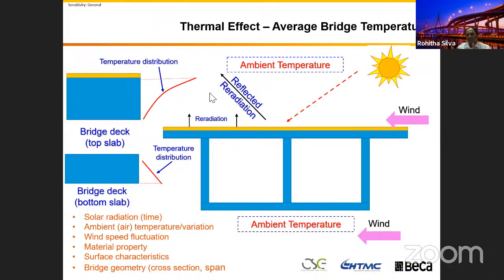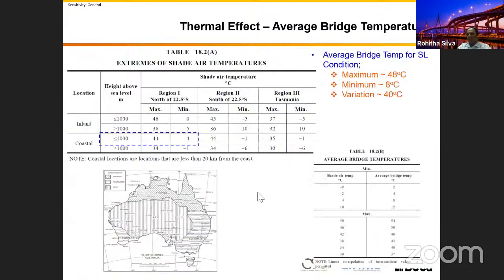If you know the strain, you can easily calculate the equivalent bending, axial, and residual forces in the structure. I will do an example. I will show it to you. Then you will see that because of this differential stress distribution, there is always residual stress within the bridge. So we need to be really careful when we are designing this.